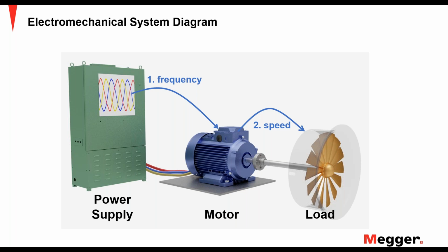And the difference between the spinning of that rotor and the spinning of the electromagnetic field in the stator, that difference is slip. The slip is what's going to give us that torque production. So the difference between the spinning electromagnetic field and the spinning rotor is slip. Slip is directly related to torque. So if we put more load on this motor, it's going to slow the rotor down, draw more current, producing more torque.